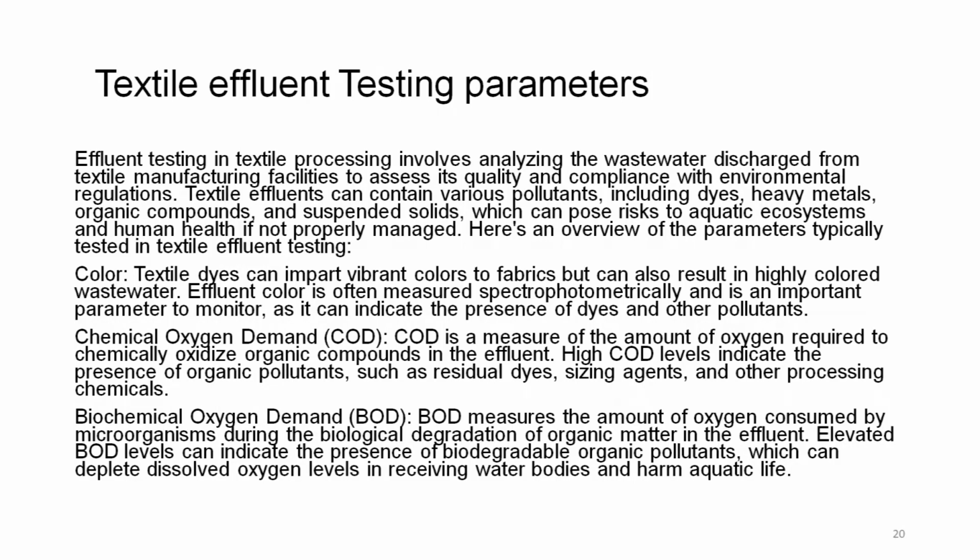And we learned a while ago that color is one of the most apparent problems that we see. Textile dyes can impart vibrant colors to fabric, but can also result in highly colored wastewater. Effluent color is often measured spectrophotometrically and is an important parameter to monitor, as it can indicate the presence of dyes and other pollutants. Chemical oxygen demand, COD. Repeatedly I am telling that these are the main culprits of textile effluent.